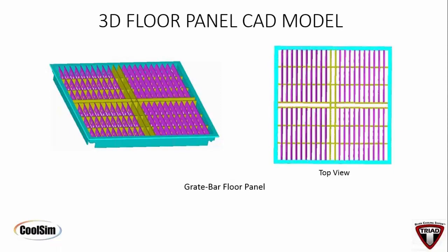Yeah, now if you look at this straight on, without knowing what we've learned, you would say, well, that's pretty good, right? Air's coming straight up through the floor, and then these would bend it one way, and then these on this side would bend it the other way. The flaw in that conclusion is that the air is coming straight up out of the floor. It doesn't. The air moves horizontal under a floor, at least many floors, unless they're very, very, very deep.